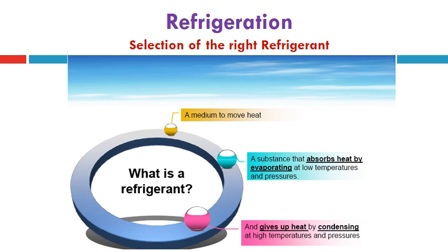Also, the condensing temperature, which corresponds to the condensing pressure, whether using water or air, will affect the value of the condenser pressure, and then the power required by the compressor. The cooling effect will be slightly affected by the value of the condensing pressure and may increase due to the slope of the saturation liquid line discussed before, on the left-hand side of the cycle at the end of the condenser, which will be increased if using water rather than air.